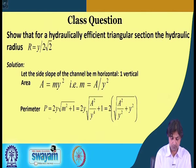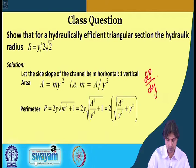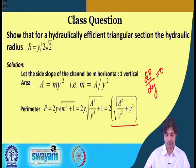So, our area comes out to be A by y square, and the perimeter also comes out in terms of A and y. So, our unknowns here are A and y. For an efficient section, what do we need to do? We need to have dP by dy equal to 0, fine. To be able to do that, we already have this equation in terms of area.